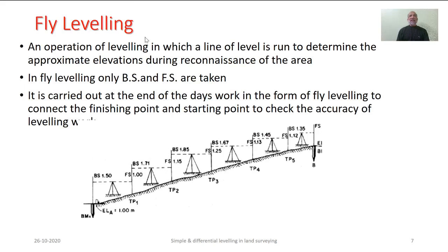The fly leveling is another category of leveling. It is an operation of the leveling in which the line of level is run to determine approximate elevations during reconnaissance of surveying operations.